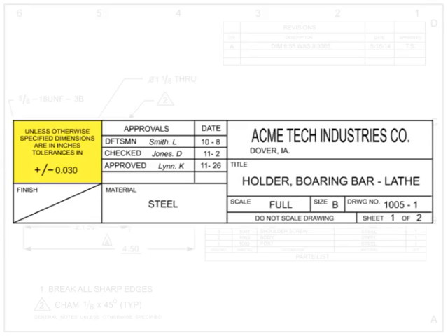The tolerances block contains the default tolerances for dimensional callouts where no tolerance is otherwise noted on the drawing. The tolerances in this block should be followed unless specifically marked otherwise. Examples of tolerances are plus or minus 0.030 or plus or minus 1/64 of an inch.